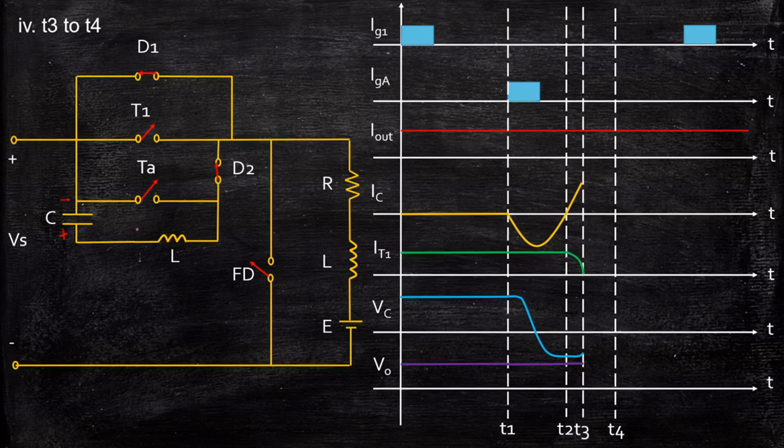So what will happen now? The current still flows through this path, through the diode, because till the case when T1 was conducting, T1 was ensuring D1 is not conducting. Once T1 is open circuited, the plus polarity will directly appear across the anode of D1. As a result, it's getting forward biased, and consequently it's ensuring that T1 does not turn on because of the forward voltage drop that the diode D1 creates. So the current starts flowing through this loop, and there is no flow of current through T1. The source current will flow only through the capacitor, through this path to the load in this particular direction, and it reaches this point.